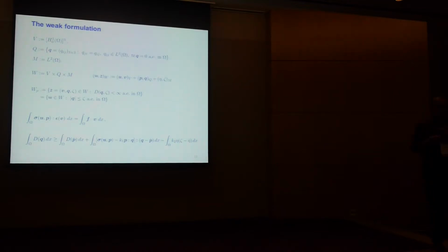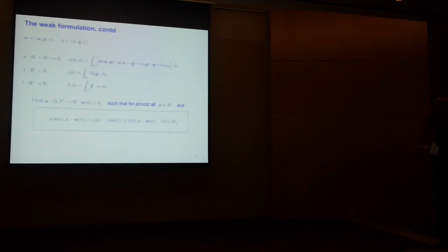So still looking a little complicated, but I can put these two together in the form of a single variational inequality by defining a bilinear form like that. So the two terms of the K1 and K2 down here, and the J term, and if I put that all together, it looks like this, which is exactly the form of that abstract variational inequality I showed earlier, which is not standard, and therefore is something which we've spent a lot of time studying, both theoretically and computationally.